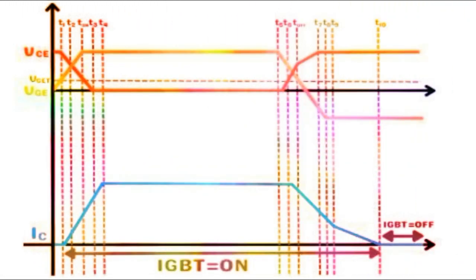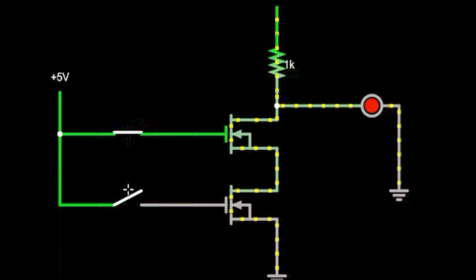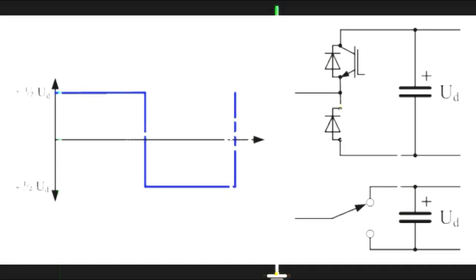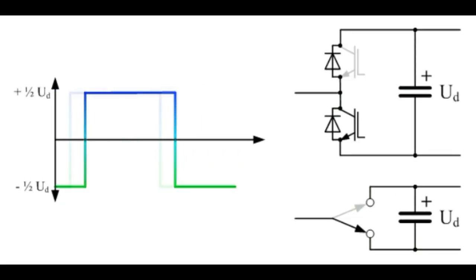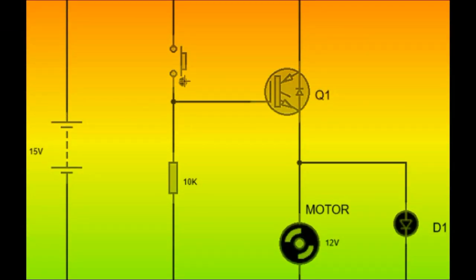The direct blocking function of the IGBT transistor is similar to that of the power MOSFET. When we use the IGBT as a static control switch, this part has the same voltage and current values as the bipolar transistor. Of course, the isolated gate in the IGBT needs less power than a BJT. An IGBT can be turned on or off simply by enabling or disabling the gate pin.